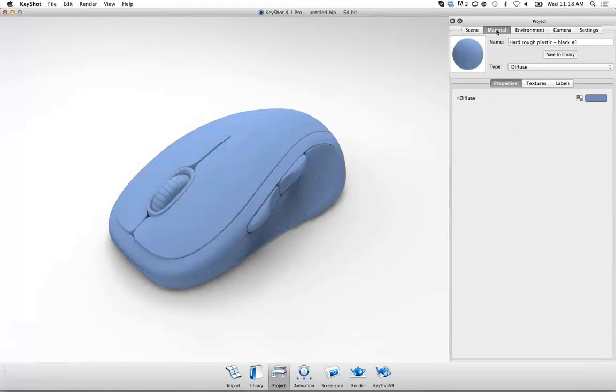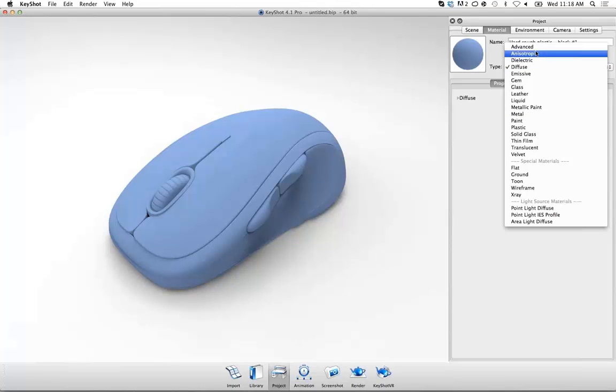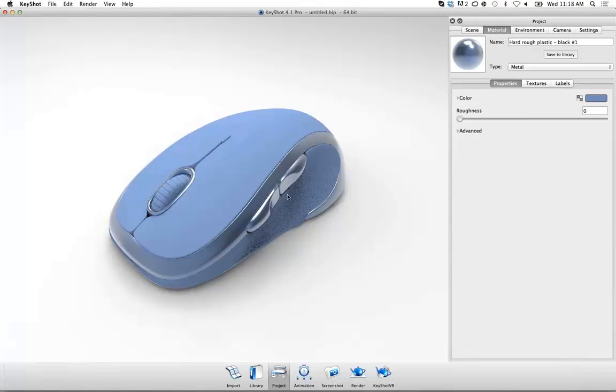What that does is automatically bring you to the next tab, which is the Material tab. This tab shows you the properties of that specific material and part, and lets you edit it to what you need it to be. Again, you can rename the material on top, just like you can rename the part. This is a good place to go into the next window we have, because you can create your own custom materials here, like let's say they're metal. See how it automatically changes it to a metal type shader.